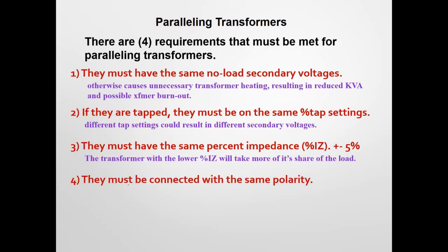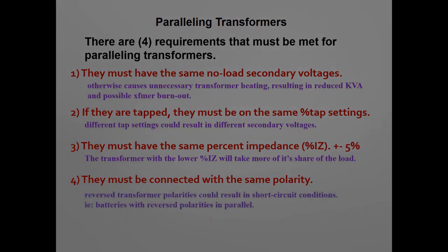And the other thing, they must be connected with the same polarity. So you don't want to mix up which is X1 and which is X2 on these. And this is definitely a big thing when we get to three-phase transformers. Three-phase transformers are just three single-phase transformers connected up in either Y or delta. And if we have the wrong polarity, we're going to have a short circuit and a little bit catastrophic.